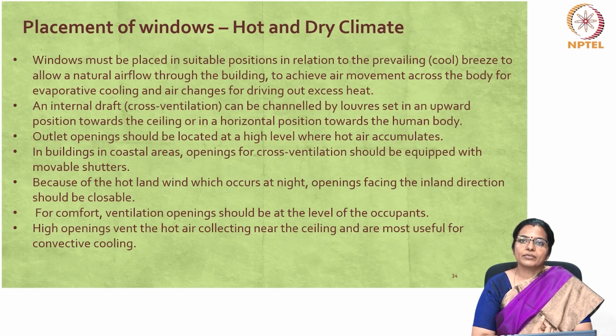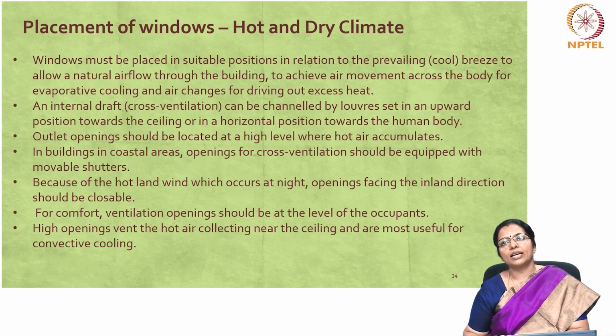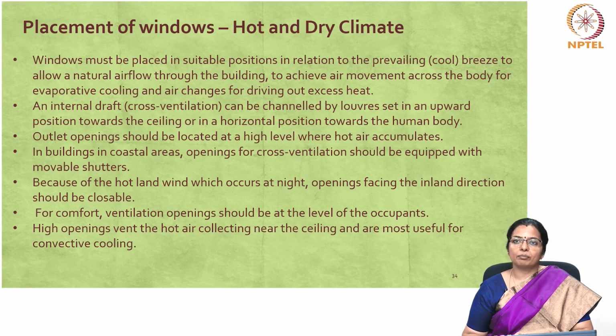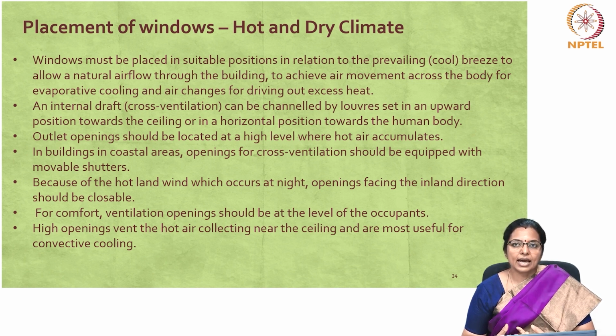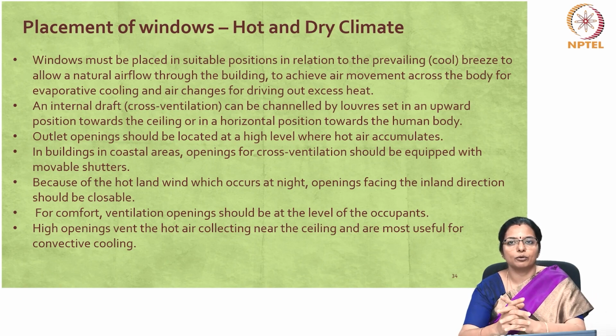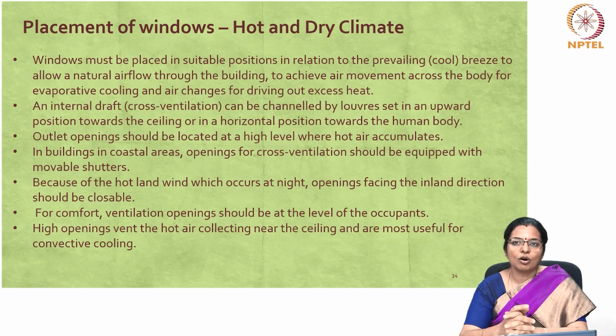Let us look at how windows should be placed. Windows should be placed in suitable positions in relation to the prevailing breeze, which should be cool to allow a natural airflow to the building, to achieve air movement across the body for evaporative cooling and air changes for driving out excess heat. An internal draft like cross ventilation can be channelized by louvers which are set in an upward position towards the ceiling or in a horizontal position towards the human body.